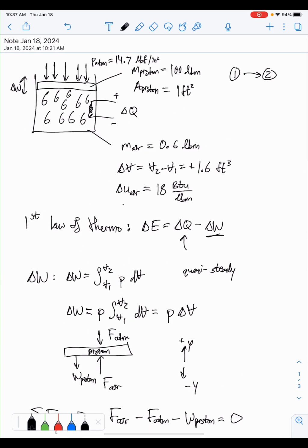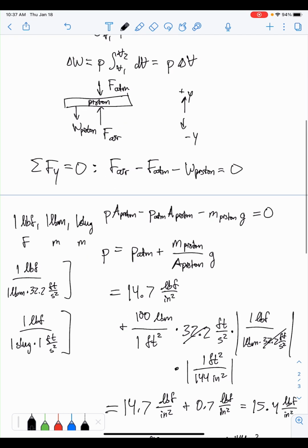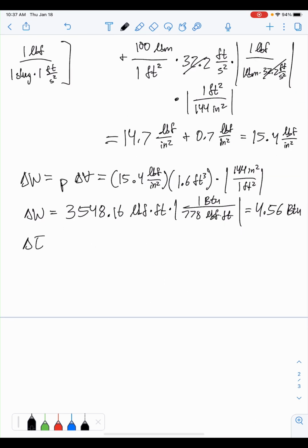In terms of this equation, we have this. We don't have energy yet, but we can use internal energy to get the change in energy of the system. To keep it really brief, change in energy can be expanded to change in kinetic energy of a system, its potential energy, and a bunch of other stuff. But at least I believe that our system is at rest and steady state. Most of these things will be canceled out. All we gotta care about is change in internal energy. And this will change in future chapters, but at least for now, this is true. And that change in uppercase U is the same as mass times change in lowercase u, change in internal energy.